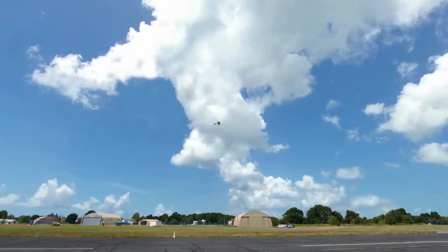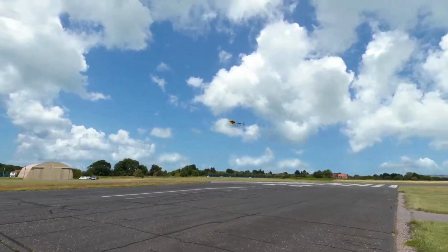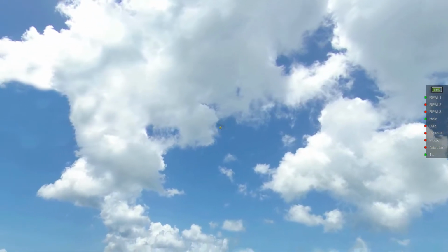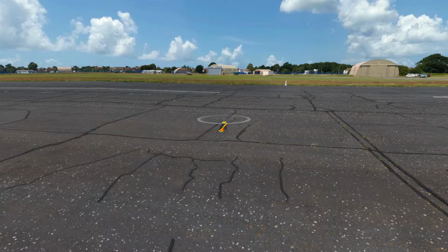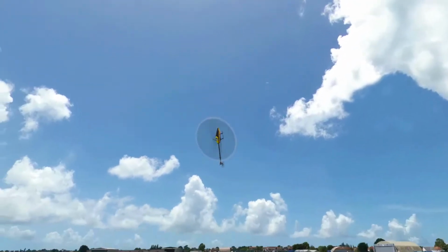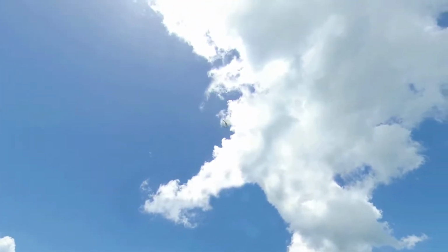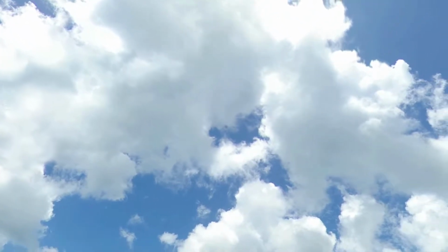Okay, a lot of people think that lift comes from the downwash behind the wing. It turns out that downwash is not a necessary part of lift. If you build a wind tunnel model that goes from one wall of the wind tunnel to the other wall, and it's a wing, okay, but it doesn't have a wing tip. So it turns out that the airflow that comes in, and then it sweeps up, exactly meets the leading edge, then it comes down and leaves the trailing edge, and it comes back to the exact same level that it was beginning. In other words, there is no downwash. But the wing still produces lift.